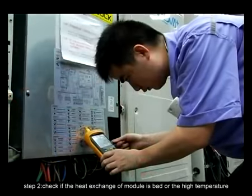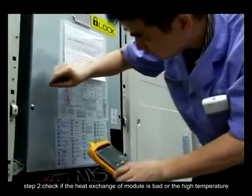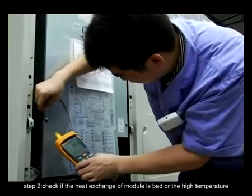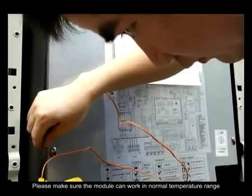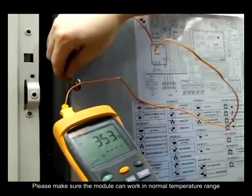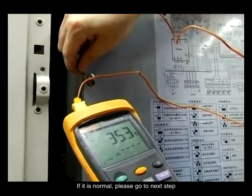Step 2. Check if the heat exchange of module is bad or the high temperature inside electric control box leads to module protection. Please make sure the module can work in normal temperature range. If it is normal, please go to the next step.